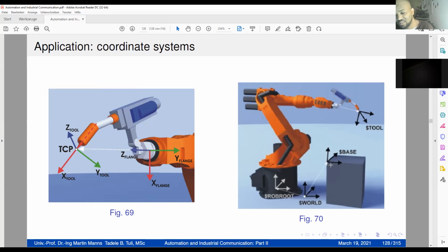You could consider it as a fixed reference frame and then generate your trajectories. But that is not quite true, because it is a computed reference frame, computed with respect to the robot root frame or maybe the world reference frame. You always have the possibility to configure your coordinate systems along the workpart.